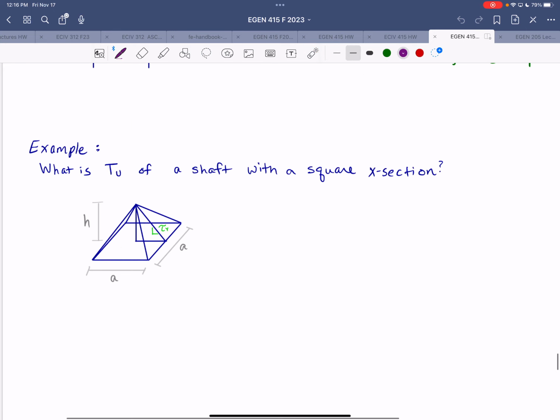And remember that the whole point behind the sandhill analogy is that the slope of that hill is going to be equal to the yield stress, right? Because then that means the entire cross section has reached that yield stress. So we have the yield stress equal to H divided by a over 2, just using geometry. So we can write H is equal to that yield stress times a over 2.